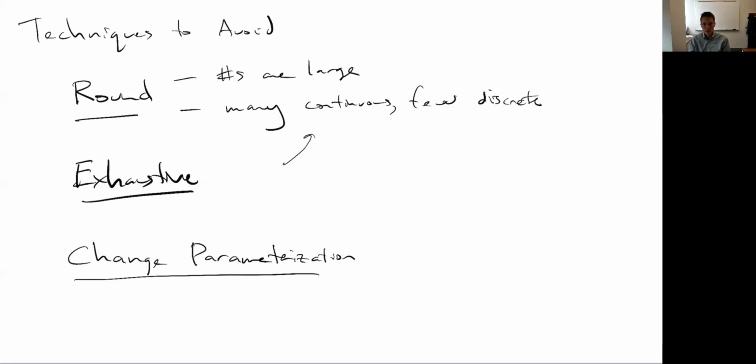But I could also parameterize it maybe by a curve, right? Maybe there's like this smooth curve that occurs here. Or maybe I parameterize it using a radius instead of a diameter. That doesn't really make a big difference, but there are many options of ways I could describe it. And those are my design variables, right? So if I change the way I describe the problem, it may suddenly become continuous. This often requires a fair amount of creativity and maybe some experience, but I'm just making up an example on